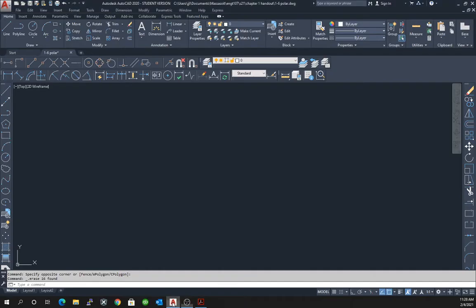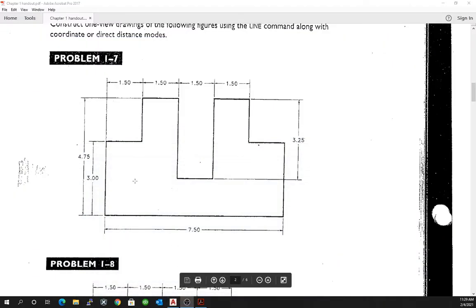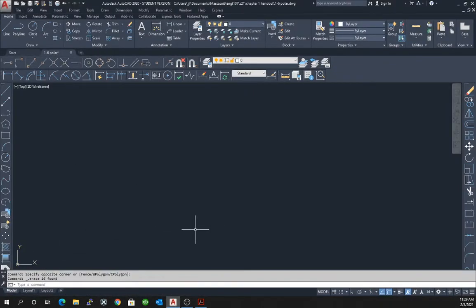So go into AutoCAD. And quickly, if we take a look, there's no arrow here. So there's nothing that tells us where our origin is. So we don't have to pick any kind of origin. So we can start anywhere we want. So we're just going to start here. And then we're going to simply type at 0, 3, because we're going to go 0 in the x dimension and up 3 in the y dimension.